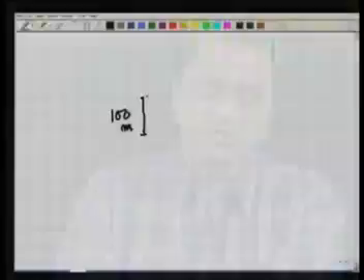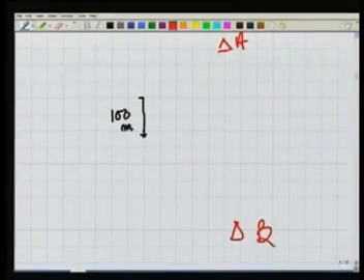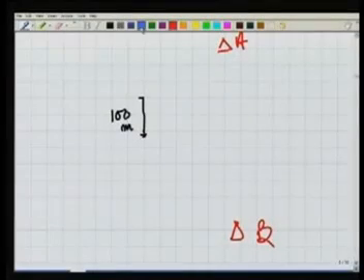I could find a stretch of the ground there which is flat, and I could measure a very small base length accurately. Now I want to connect it finally to this big base. The actual base for my triangulation is A and B, which we are not able to measure directly because of the problems in the terrain. It's a huge length, 1.5 kilometers of that kind of order. So what to do? We will start with this small base that we have measured, and we will try to extend it.